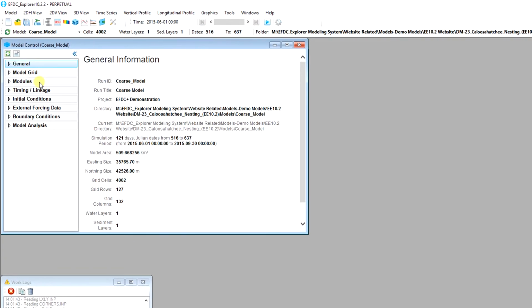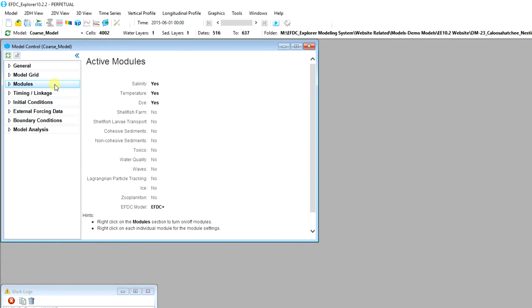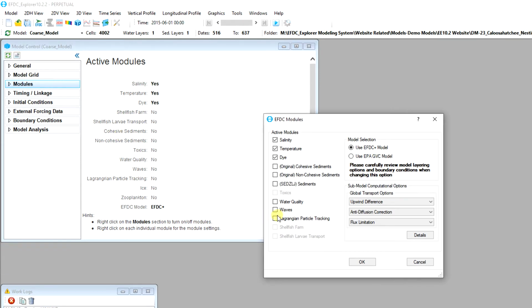The influence of wind on the flow velocity field is important while studying hydrodynamics and sediment transport in lakes, estuaries, and coastal areas. Wind effects not only induce the flow current, but also generate surface waves with a height of up to several meters. To calculate the total bed shear stress in such areas, the model must take the wave factor into account. The wave direction is the same as the wind direction. This means that the effects of refraction, diffraction, and reflection are not taken into account in the internal wave model.